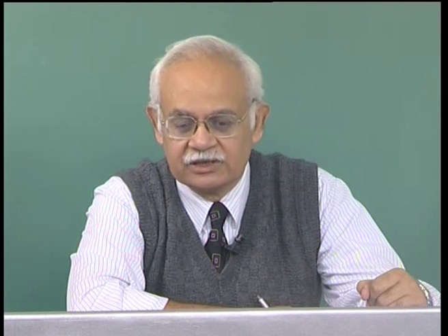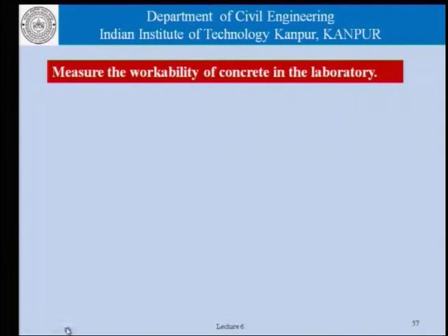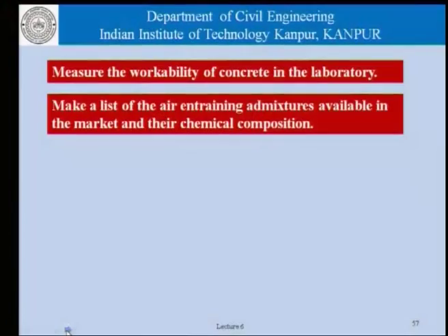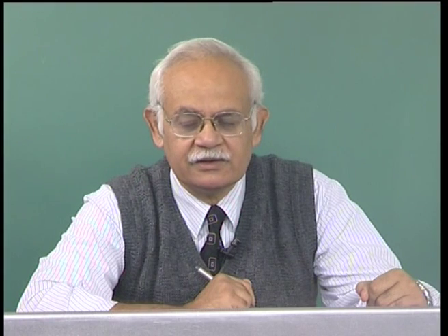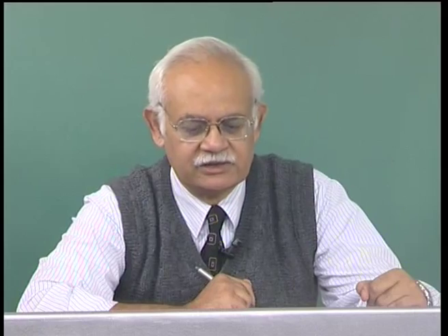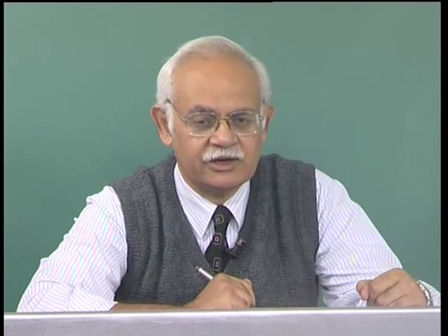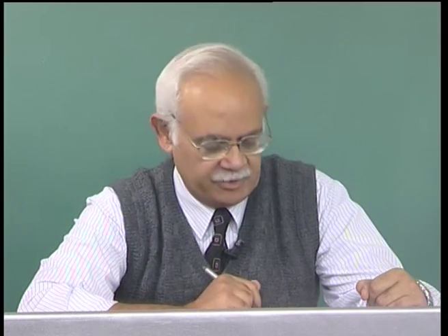I would like you to measure the workability of concrete in the laboratory and try to see how it varies once we change especially the water content of the concrete. I would like you to make a list of air entraining admixtures available in the market and their chemical composition. It will be a good exercise to understand the chemistry involved, at least to some extent, of the interaction between the chemical admixtures and the cement and so on in terms of the air entrainment.